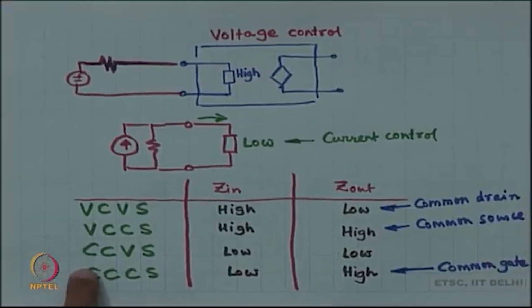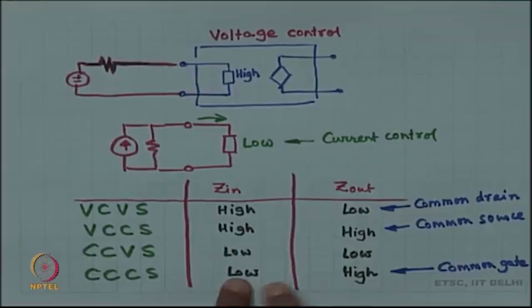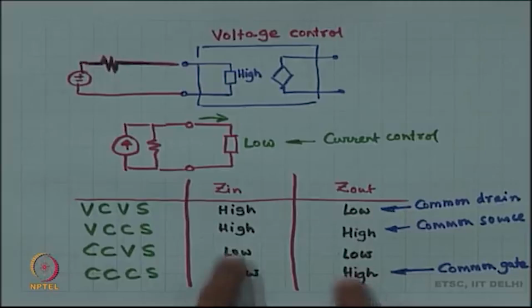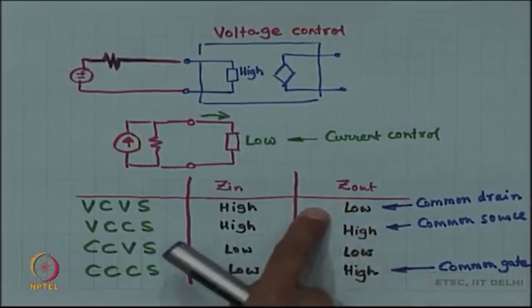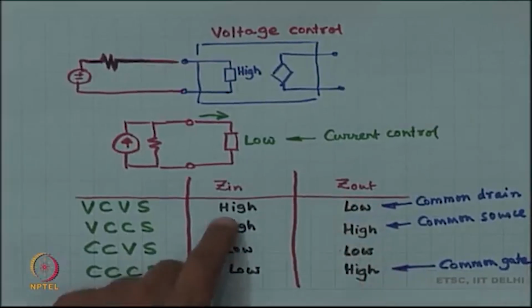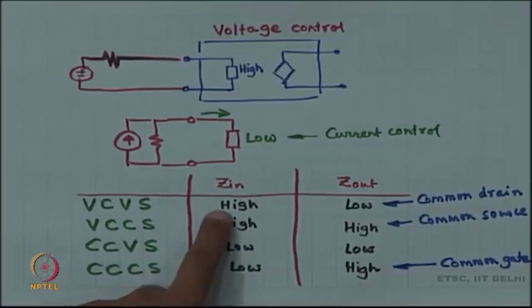Okay, I do not have an example right now of a current controlled voltage source. Maybe if you want to make a current controlled voltage source, you place a current controlled current source, which has a high output impedance, and then you are kind of stuck. Then you can put a voltage controlled voltage source at the back end, which has a low output impedance. The VCVS has an infinite input impedance, so this high output impedance will not matter. So, you could do something like that.